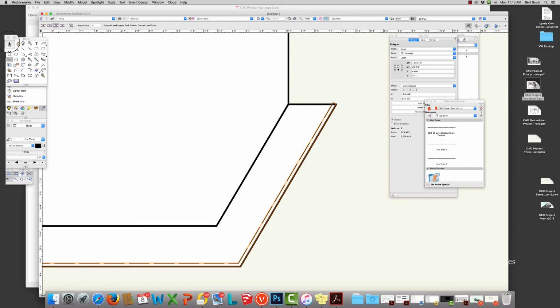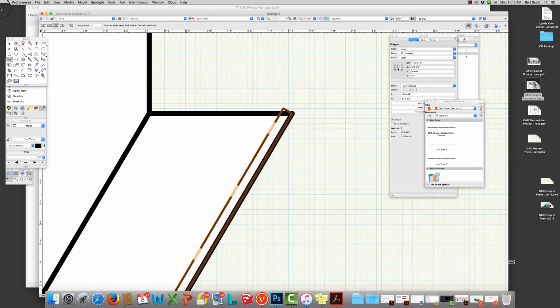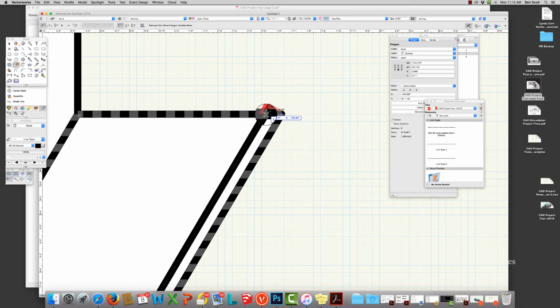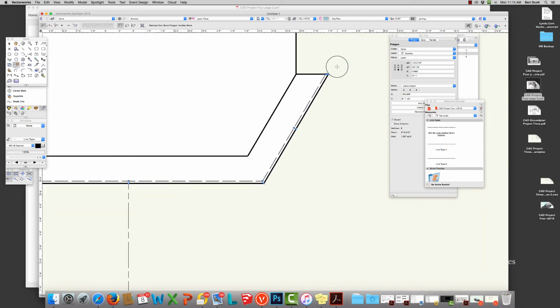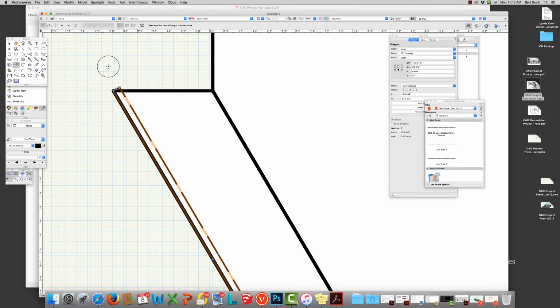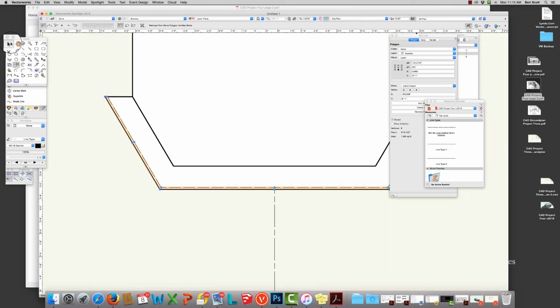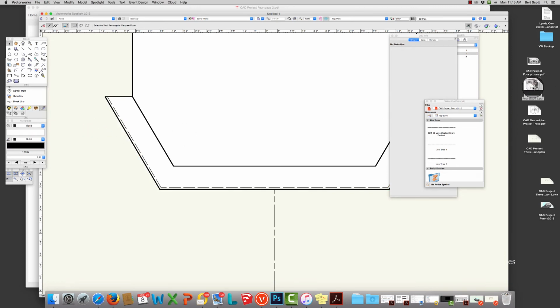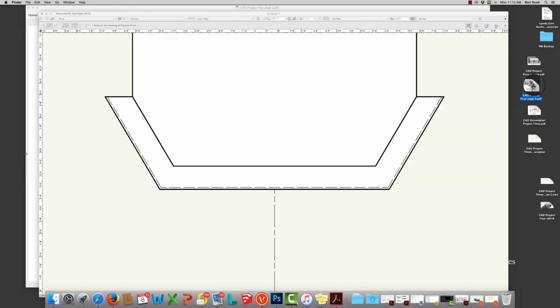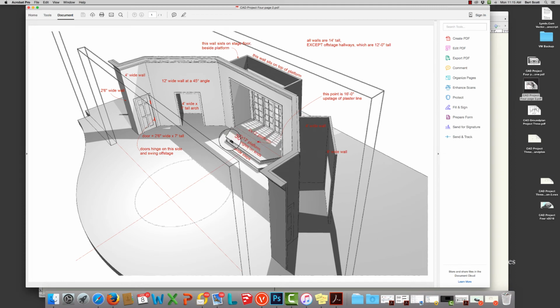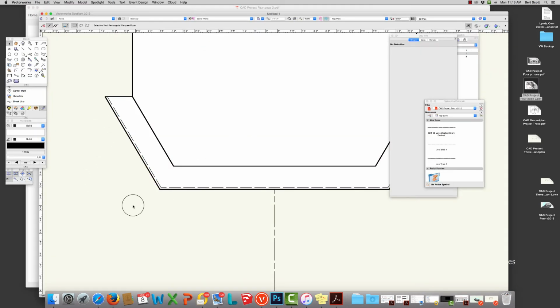And then I have to do the same trick that I did before with the reshape tool, only I'm doing it sort of in the other direction now. But reshape, holding down Shift, dragging there to make that. This is somewhat optional. This indicates the lip of the stairs, or where the stairs overhang the face of the stairs slightly. And like I said, it's optional to draw that or not. If you want to draw it, that's how you do it.